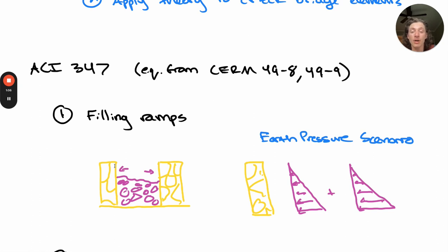This situation was already analyzed in the ramp wall component analysis, and due to the non-standard nature of the loading, the rock fill combined with the grout slurry, we opted to model this more as an earth pressure scenario, instead of pure hydrostatic pressure from the placement of concrete. So we will not be discussing this in this section because it was already discussed.